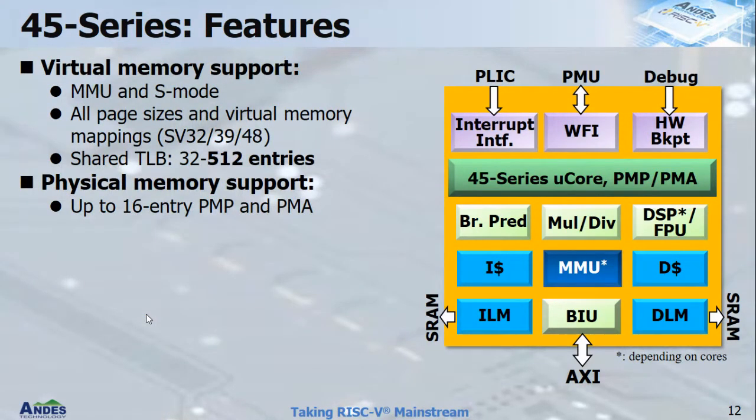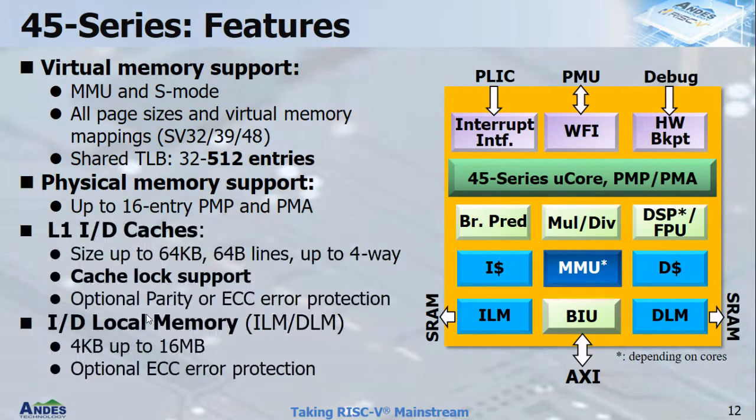Virtual memory support is very important if you want to run an operating system, so we have added this here. You have shared TLBs with up to 512 entries. And we also have physical memory support. So if you have cases where you need to protect your memory, the PMP and the PMA are quite good.